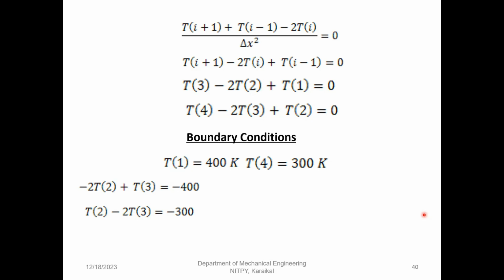So if you're going to have a pipe flow, and some jet of water or air is going to enter into the pipe, you know the pressure and velocity. It's going to come out, but you don't know the exit values. But what you know is it's going to exit into the atmosphere. You know the atmospheric pressure. That means you must model the atmosphere and then give that value. Then only you will be able to calculate the exit pressure of your pipe.